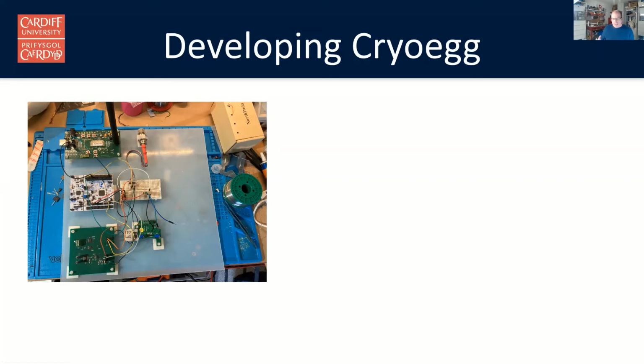And so any kind of minerals that it comes in contact with, such as in the till on the bottom of the glacier, will dissolve in the water and increase its conductivity. So by looking at the electrical conductivity reading, we can tell, is it sitting in freshly melted water, or is it sitting in water that's actually been hanging around on the bottom of the glacier for a long time? In the middle, this white circuit board has a processor on it, which is basically managing the whole system. And then at the top is a radio transmitter, which sends the signal up to the surface.